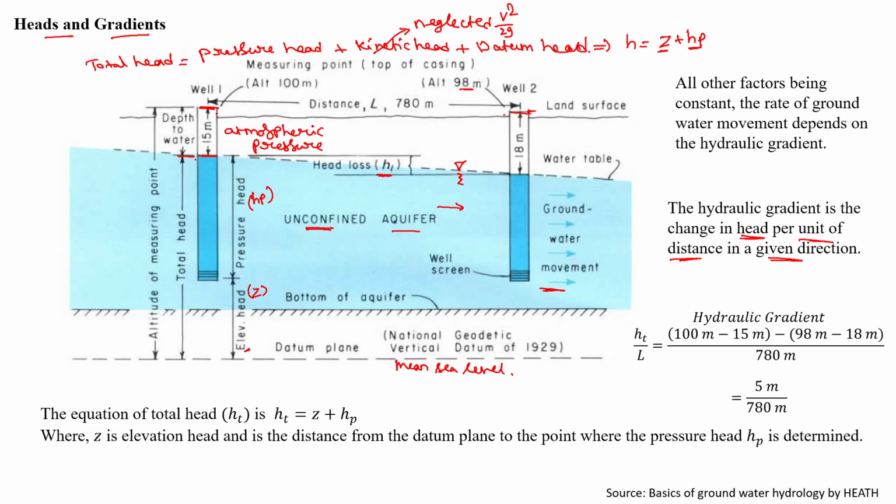In this case, what we need to do is first calculate the total head in both wells. Always, even in fluid mechanics, geotechnical engineering, or hydrology, we should always look at the total head. Even in open channel flow in the previous session 3, we calculated the specific energy. What we did was that in specific energy, we assumed the channel bottom as a datum. With respect to the channel bottom, we estimated the total energy. In this case also, we need to take the datum as a reference,